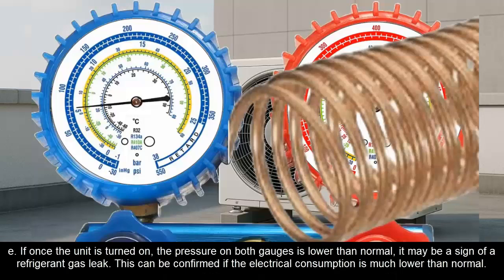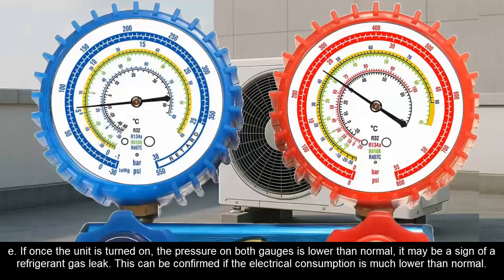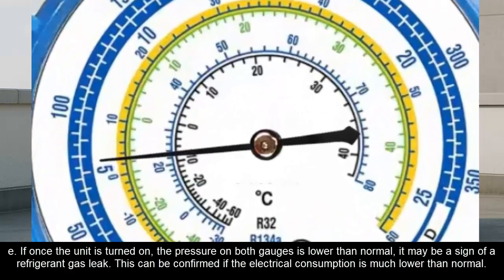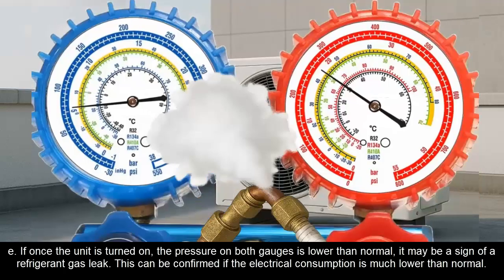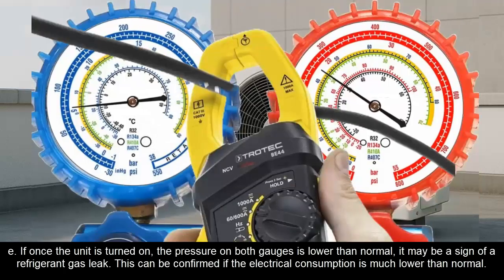E. If once the unit is turned on, the pressure on both gauges is lower than normal, it may be a sign of a refrigerant gas leak. This can be confirmed if the electrical consumption is much lower than normal.